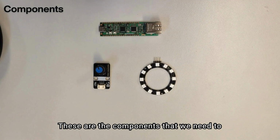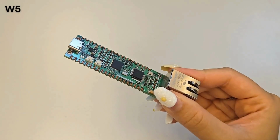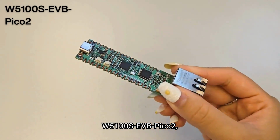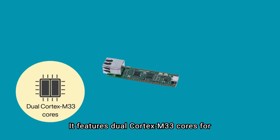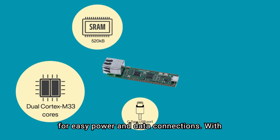These are the components that we need to use in this project. The RP2350 microcontroller board, W5100S-EVB-Pico2, is an excellent choice for IoT projects. It features dual Cortex-M33 cores for efficient processing, along with 520 kilobytes of SRAM and a C-type USB port for easy power and data connections.